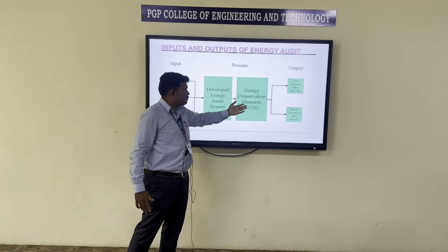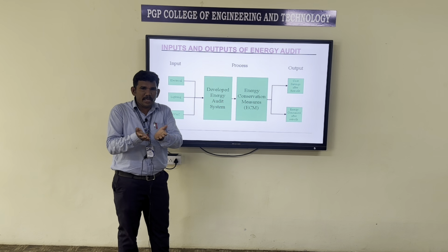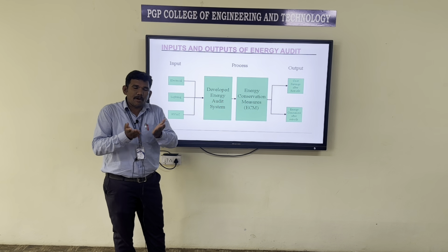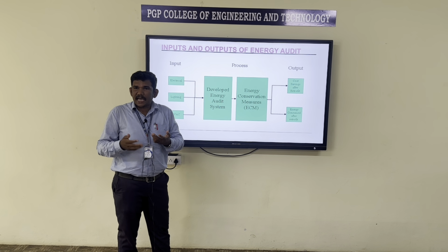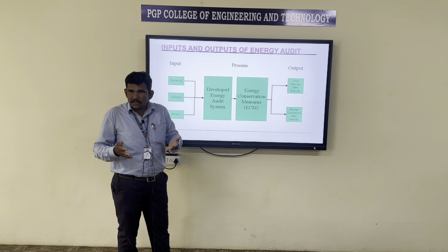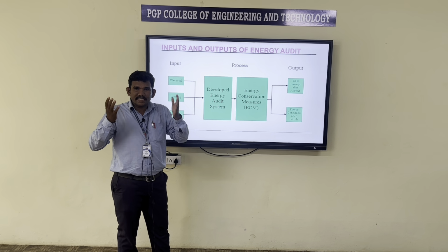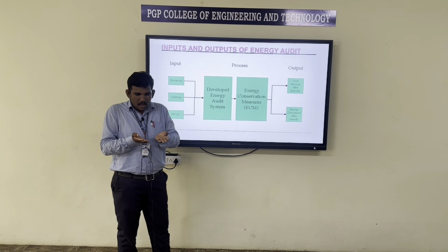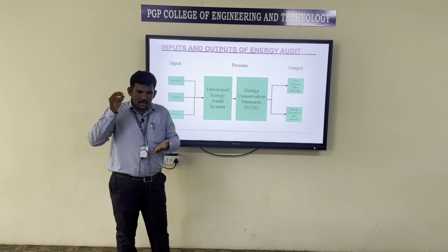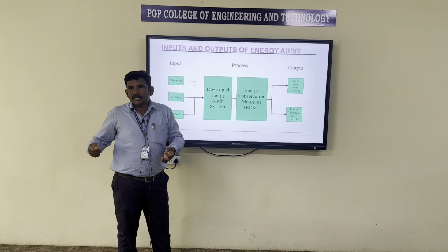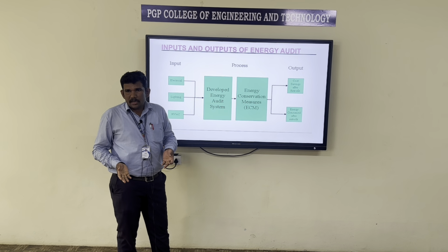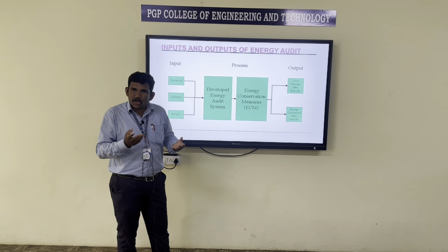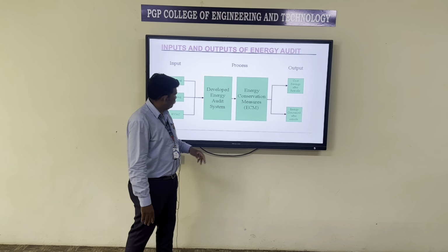Energy conservation measurements, in the sense that we are using the kit today. Today we are using the power analyzer, which is capable of showing the phase voltage, line voltage, current, power factor, all factors. All data are saved in digital format. By connecting your laptop, you can transfer the data from the power analyzer to the laptop. Even the pie charts, everything will be available.